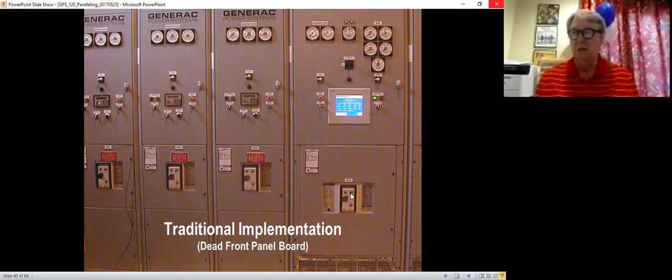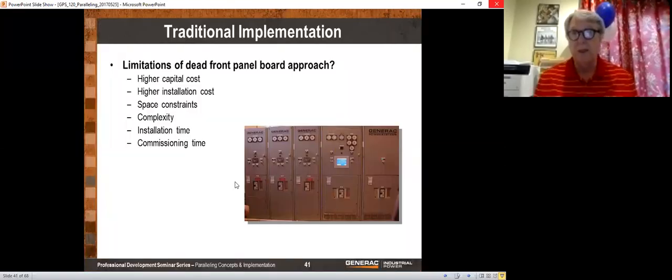Here's a system which has one master controller and then 3 generators. You can see it's very large, it's very expensive, it requires a building to be in, and none of this is necessary. We have the whole master controller on the circuit board that gets rid of the master section, and we simply put these contactors or the circuit breakers on the generator. Now you just get rid of this. There's really no reason for paralleling switchgear with today's modern control systems.